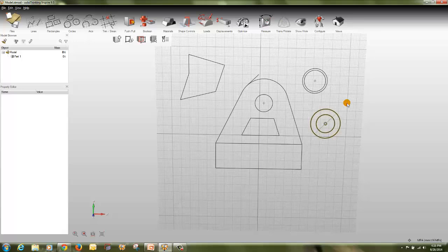So parallel, vertical, horizontal, and some more, the perpendicular constraints also. So I will show you that. So let's create one line, another line, right click, control, left click, select both the lines, parallel constraints. So these will become parallel. Perpendicular constraints. So this will become perpendicular. So you can move it. You can move this line. Like this, control, perpendicular. So now they will become perpendicular lines.